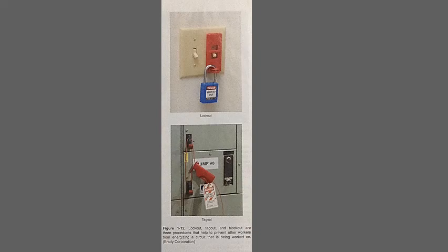Replacing damaged equipment or making a trip to the hospital usually takes more time than turning the power off. "I have insulated tools." It's also not a reason to work on energized equipment. Turn the power off and use the lockout, tagout, blockout methods to ensure that nobody else turns it back on.